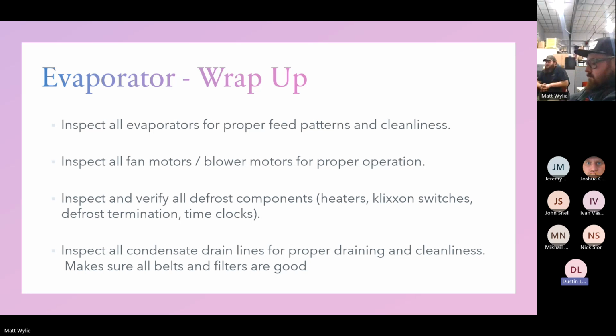My defrost energized for a split second, so I know the defrost worked. I know it went into defrost. And so I pulled my X wire off the termination, tried it again, and it defrosted just fine. So we went through 3 time clocks, pulled the X wire off, wrapped it in wire nuts, and ordered a new termination the next day. So if you ever do have a defrost time clock that seems like it kicks right back out, if it has a termination wire, pull that off and check it again before you condemn the time clock.